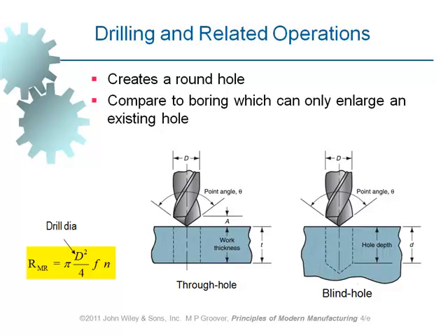The most widely used drill bit angle is 118 degrees, but anyway, there are some other angles which are being used. That's the most commonly used angle for most materials.